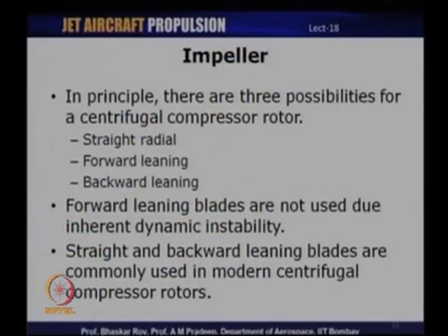Following the impeller, we have a diffuser. In fact, the diffuser again consists of two different sections. We will discuss that also. One section is a vaneless diffuser and the other is a vane diffuser. And then out of the diffuser, the flow exits and goes into a collector or a volute, which is basically the discharge of the compressor. So, let us look at the impeller of the centrifugal compressor first and see what is basically the function of an impeller.